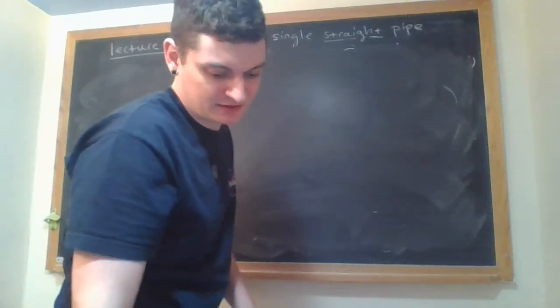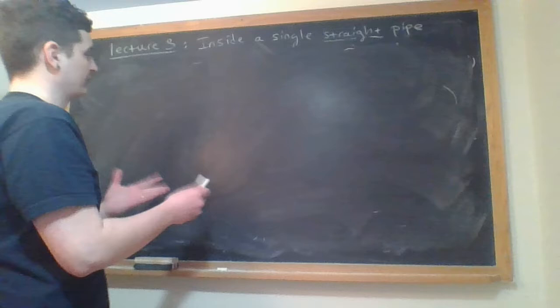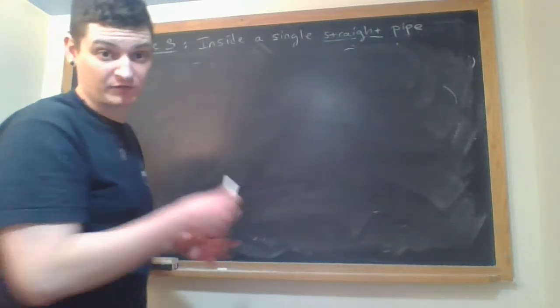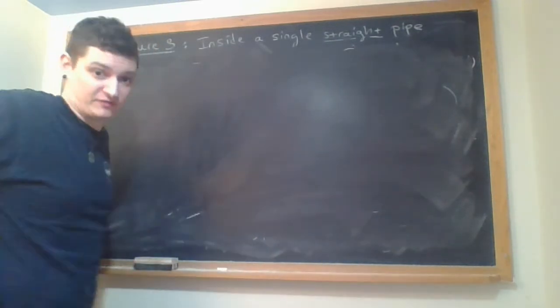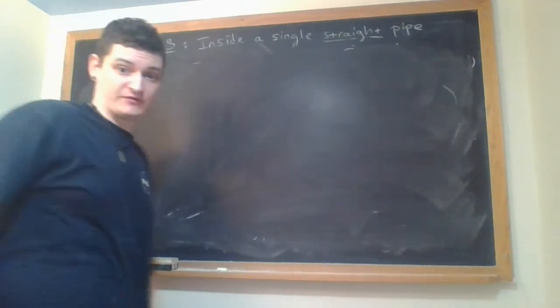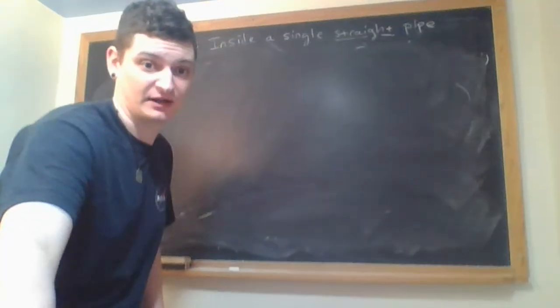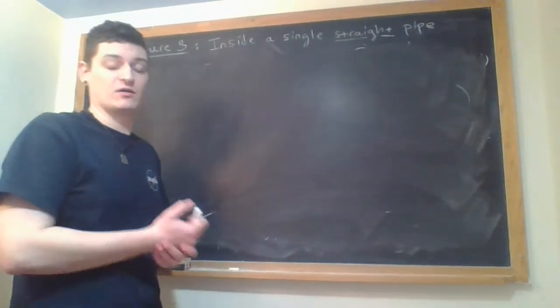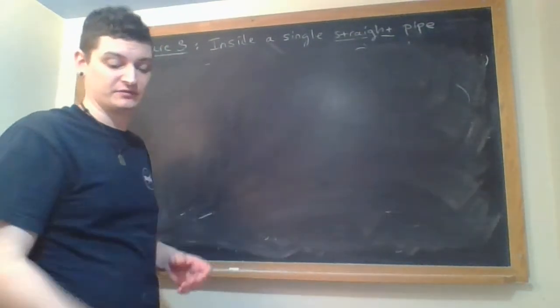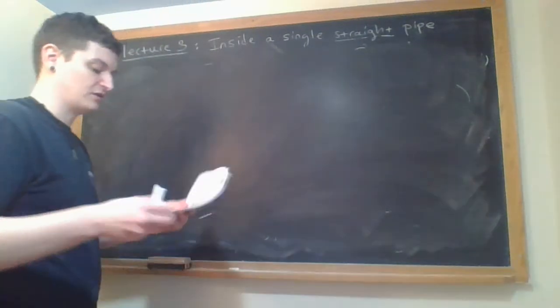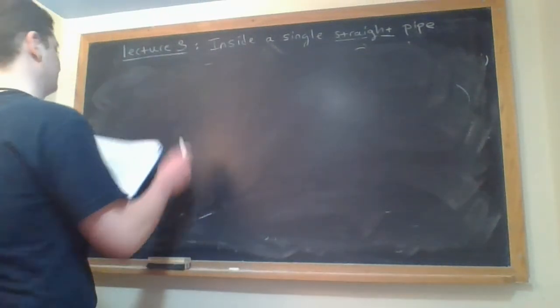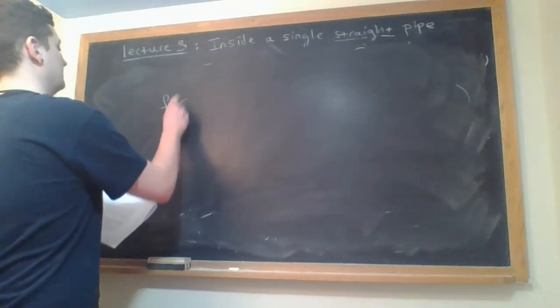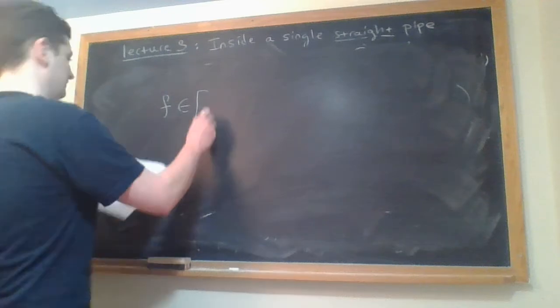So just so you can get a sense of these friction factors, now that you're going to have to calculate them for all piping problems, one of the first things you should do if you have a pipe problem is get that friction factor, because you're going to end up wanting to know how much energy it takes to get the fluid through the pipe. So a good thing to see is that these friction factors usually lie